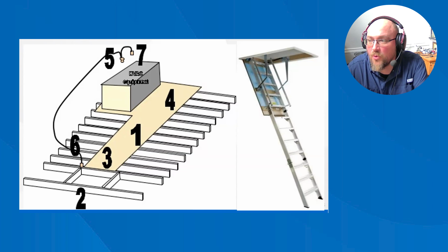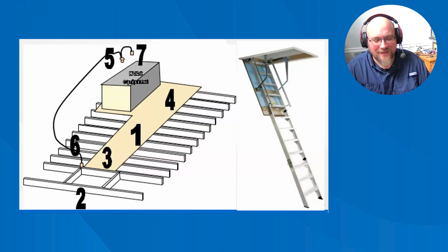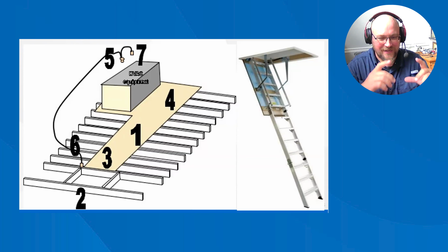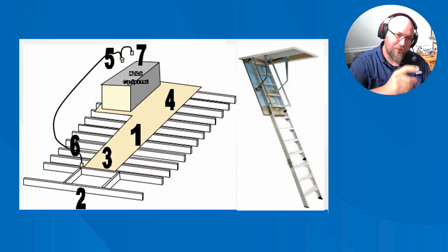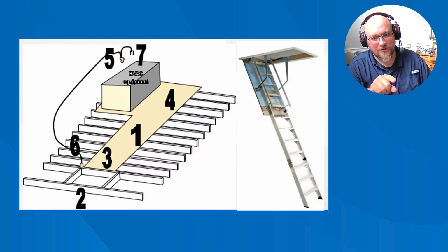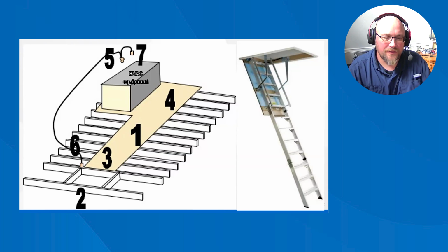Fastened with improper or missing nails or screws. If you've been in the industry any amount of time, I think it's a picture that most of us take where there's actually a sticker on the attic pull down stairs that says drive nail through bracket, and they'll drive a nail right next to the bracket or not through the bracket, or not through that side of the pull down stair framing at all.